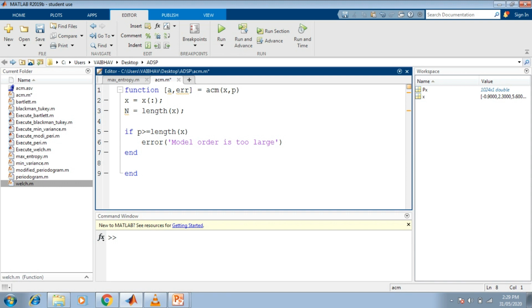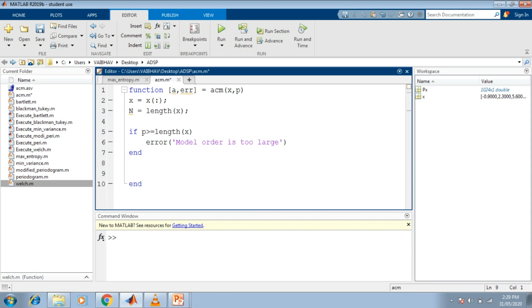Now afterwards we require the convolution matrix with the help of x, that is the discrete-time random process, and small p as discussed before. So for that purpose we expect the output in the form of a convolution matrix denoted by capital X, which can be obtained by having a definition of the function as in the previous cases, convm here, where the input accepted is x comma the order p plus 1, and a semicolon to end this particular Matlab statement. So here we save this much of the script, and now it's time to generate this convolution matrix function.